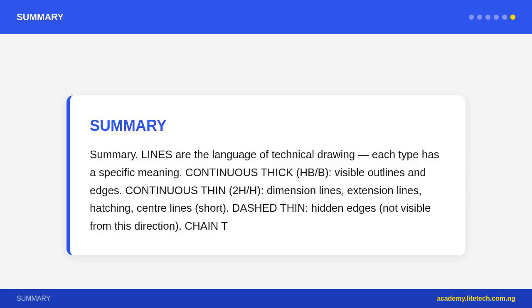Chain thin, alternating long and short dashes: center lines of circles and cylinders, axis of symmetry. Break lines show that the object is longer than drawn. Rules: consistent line weight, sharp pencil, confident strokes, construction lines barely visible. Lettering: capital letters, upright, uniform, clear. Center lines must appear on all circles.